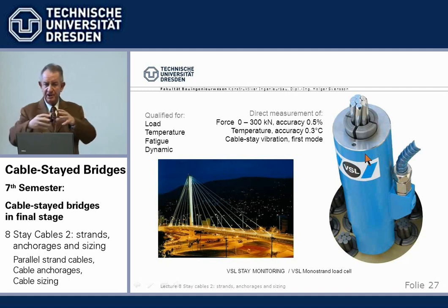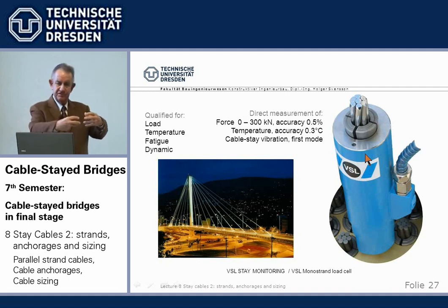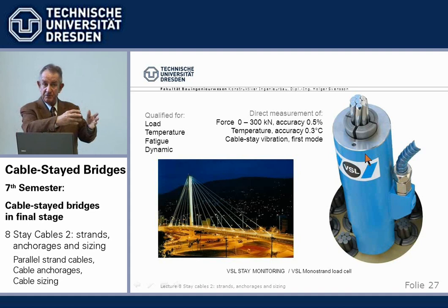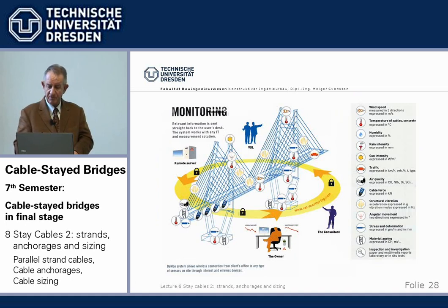There can be changes in force due to shrinkage and creep, or breaks somewhere, or change of support conditions if a bearing goes, all sorts of possibilities. So we just check the force stays the way it should. And together with other things, on a permanent basis, we can measure them here.